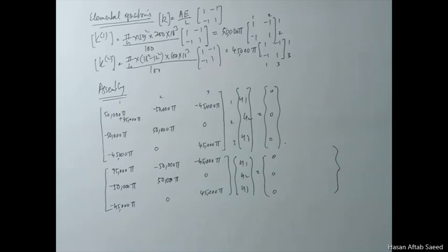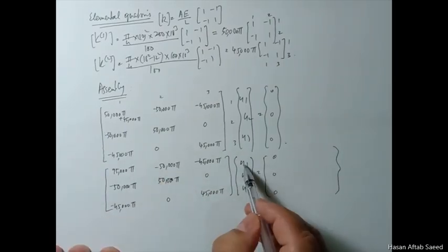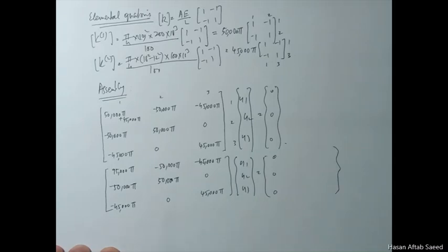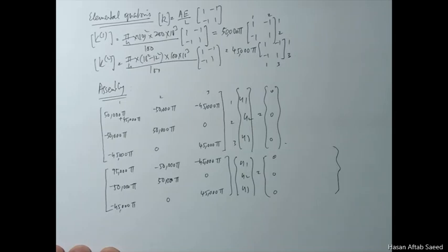Now you have to apply the boundary conditions, and just recall what those boundary conditions are. Number one, u1 is equal to 0. I could apply it in many different ways. Because it's 0, I could just remove this, but I'm going to use the simple penalty method for this one and the MPC method for u2 and u3. So let's recall what boundary conditions are there for us. u1 is equal to 0 specified.